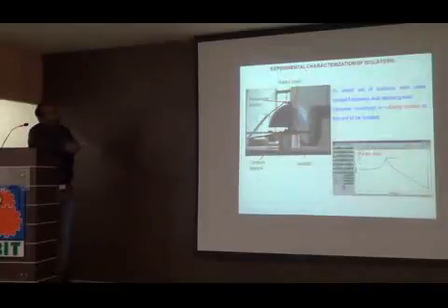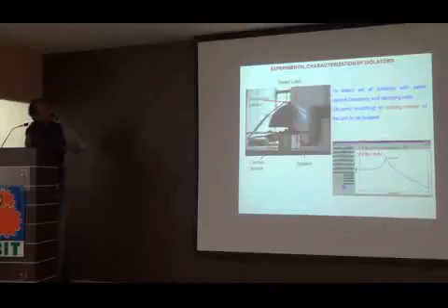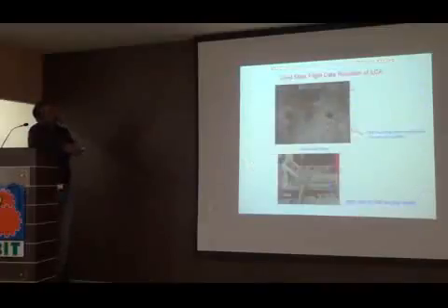Then suppose any isolator is given to you, how do you test it? See, the manufacturer may give you a catalog telling what to do, but you should have your own rated load. You put it on that, excite it to the specification given by the manufacturer, and see what the transmissibility is. In the transmissibility curve, you will get some frequency. That frequency should be the same for all the isolators that you are selecting to use. That's what we call dynamically matched.